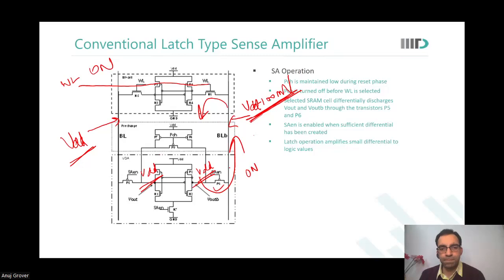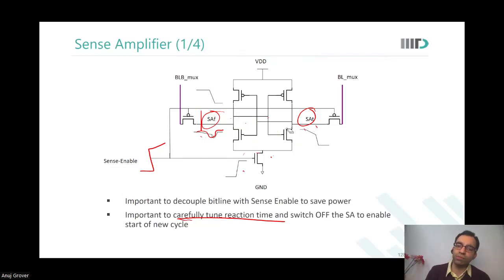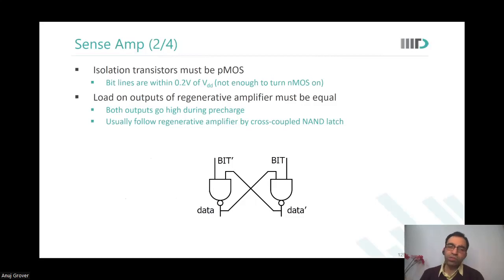Sir, can you also please explain, what was in the slide? There was reaction time mentioned. So what was that? Reaction time is when I turn the SAN on. After that, after how long will the outputs SAT and SAF be latched as 0 and 1? That is the reaction time. So, how quickly you can resolve. And that tuning will be depending upon the sizes of these transistors, right? Yes. So tuning by me, you mean how should I size these transistors? Yes.